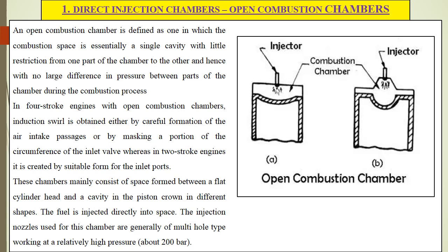An open combustion chamber is defined as one in which the combustion space is essentially a single cavity with little restriction from one part of the chamber to another, and hence with no large difference in pressure between the parts of the chamber during the combustion process. It is nothing but a space provided in the main combustion chamber. Such a cavity is provided in the piston.